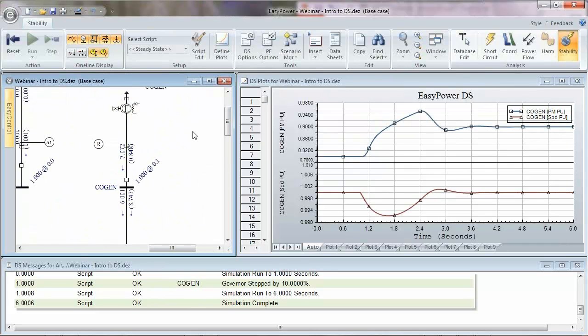we had steady state droop. Oh, do you know what? Not this one either. This one must be a form of isochronous as well. But you could have it in droop mode if you wanted to. Droop mode means that with a step load and power, we would see the speed drop slightly.